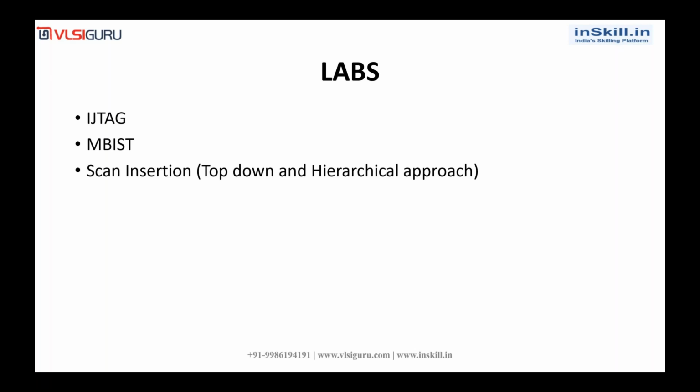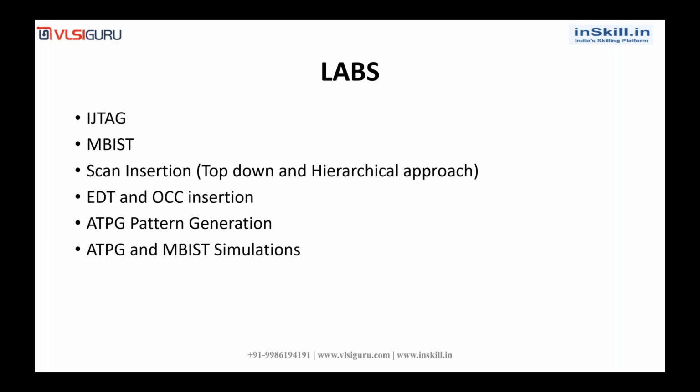So this was regarding the theory part. And in labs, we will be covering JTAG insertion, MBIST insertion, and scan insertion. There are basically two approaches: one is top down and the other is hierarchical scan. We'll be covering both approaches, EDT and OCC insertion, ATPG pattern generation, and ATPG and MBIST simulations. So all these things we will be covering.